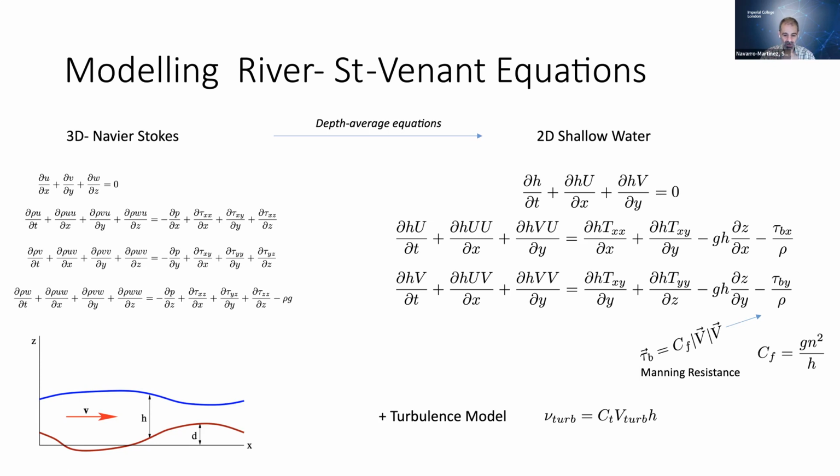We validated this by comparing the depths that they measured at the dam. So we were quite okay that at least we got very similar results. We know the depth of the river at the initial point, and we got very similar depth. So it's okay. We ignore certain small affluents. We have to, because we cannot do everything. And some bigger affluents were just added like a source of mass. We assume that the body was not going to go upstream on affluents. Not sure that adding more detail will add. I mean, this is still very uncertain.